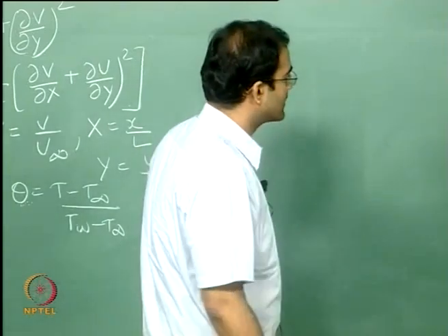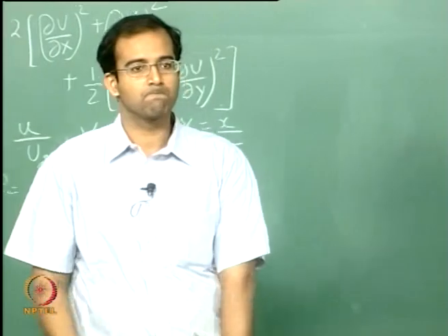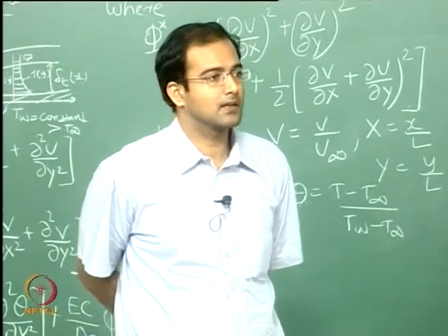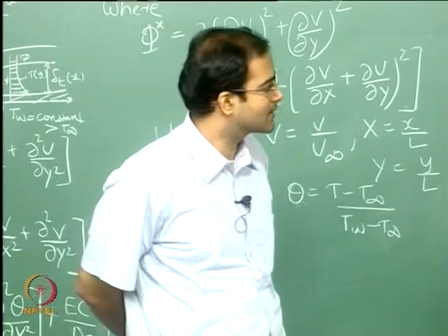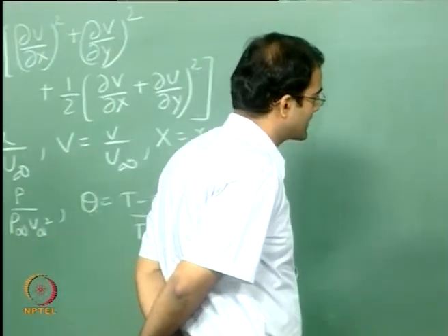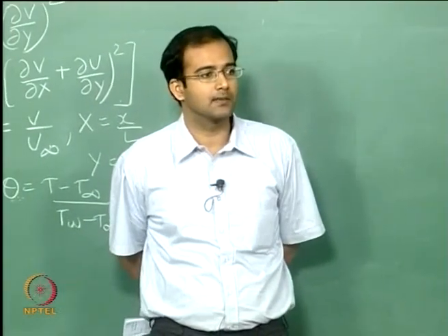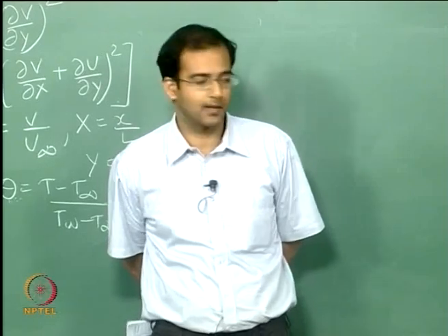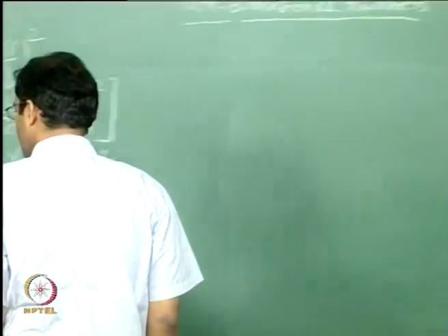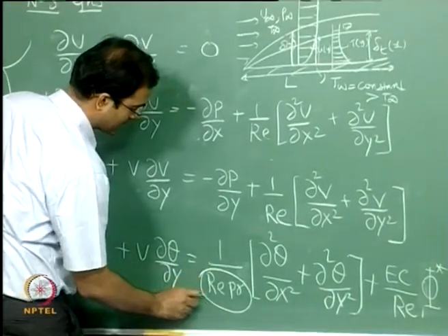Can you think of any other non-dimensional numbers in heat transfer, related to convective heat transfer, for example? Okay, the Stanton number, again it is an extension of the way that you are defining the Nusselt number. It's simply the ratio of Nusselt number to the Peclet number. Sometimes the Reynolds number times Prandtl number is also referred to as the Peclet number.